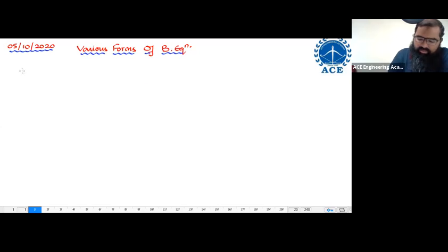There are three types of energy involved. One energy is pressure energy. So when I write P over here, please understand it is pressure energy. The second energy is kinetic energy. The third energy is potential energy. Potential energy, remember, is always represented by capital U. So basically, Bernoulli equation is saying under ideal conditions, the sum of these three energies is supposed to remain constant.